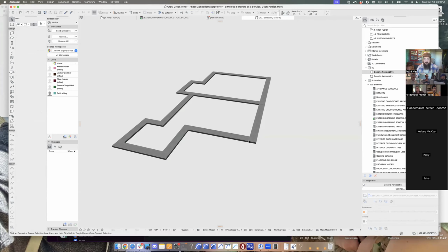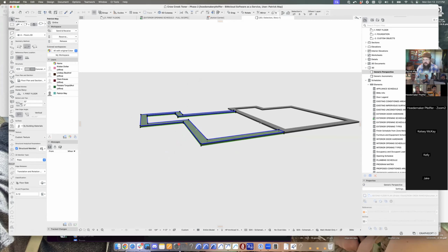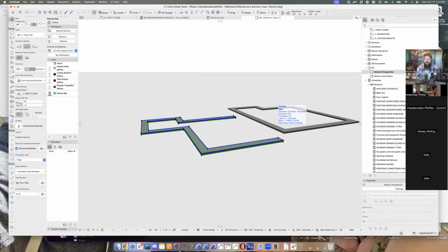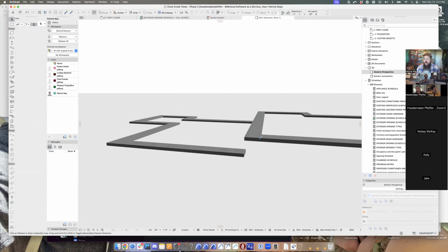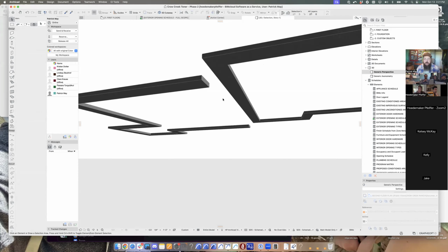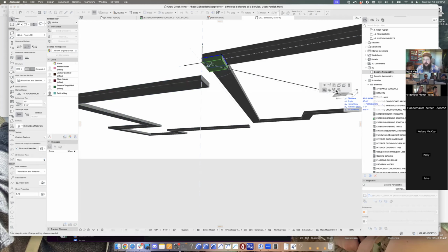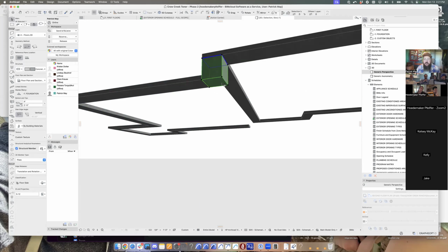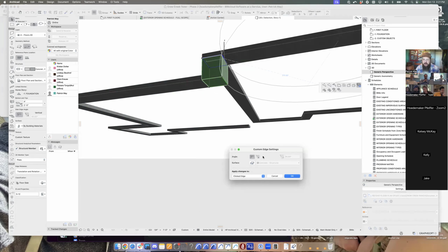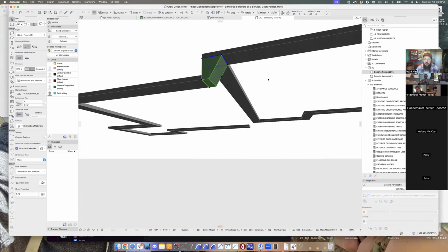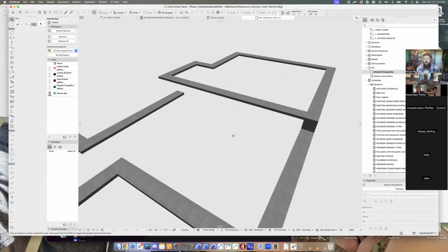And if I isolate these out in 3D, you can see here. So if this is, let's say, 4 feet below, we'll hit Command 9, Control 9, and then -4. That'll drop that down 4 feet. But I want to connect these two slabs. So what I could do is draw a slab here. Using the pet palette, I can then extrude this one to here. Because we're not going to have a big chunky pillar right there, I could say that this has a 60-degree edge or something like that and chamfer that in for a stepped footing.